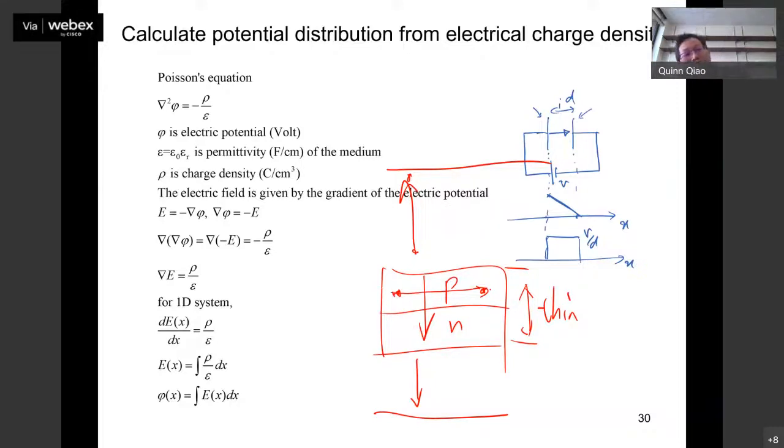No, I'm talking about when I am doing simulation of that using the Silvaco TCAD. Okay, simulation, then that's fine. Yes, I'm doing simulation in the Silvaco TCAD. I'm trying to find out the bending in the conduction band and valence band due to the grain boundary.